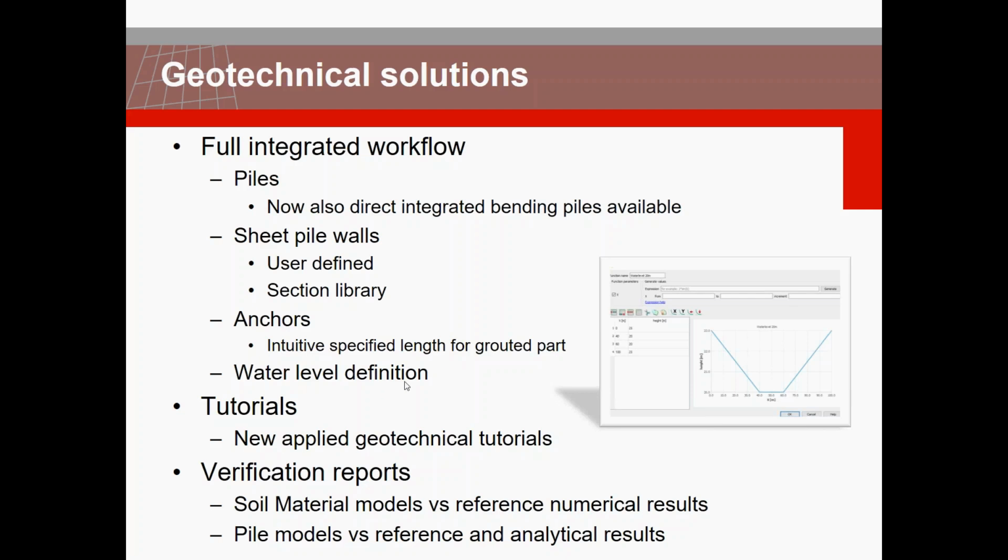Definition of the water level or phreatic level became very easy in 2D and 3D based on the position that you have at the geometry. You can define the water level and go through the dewatering or release of the water and recall these water tables in the stage construction and consider the staggered analysis.